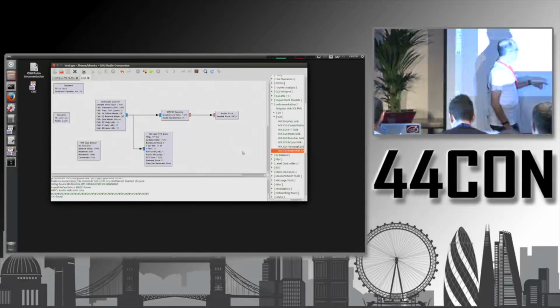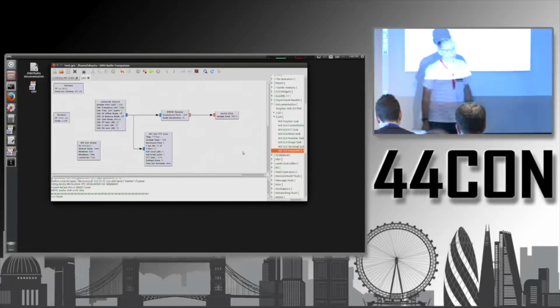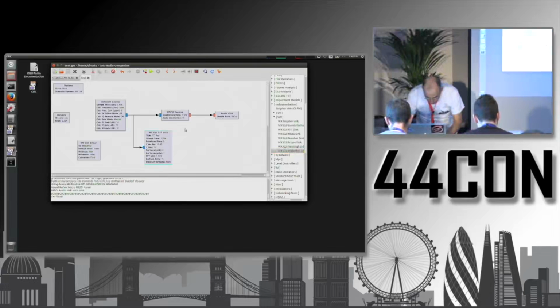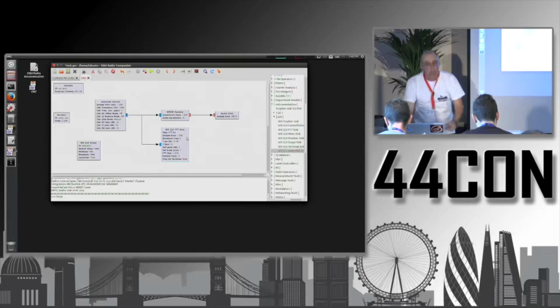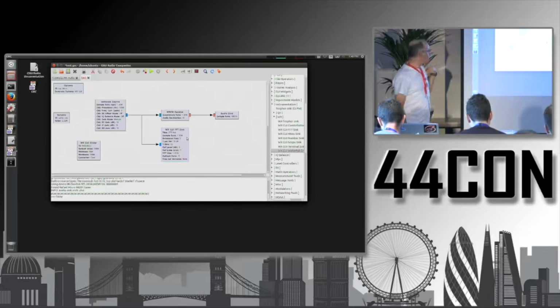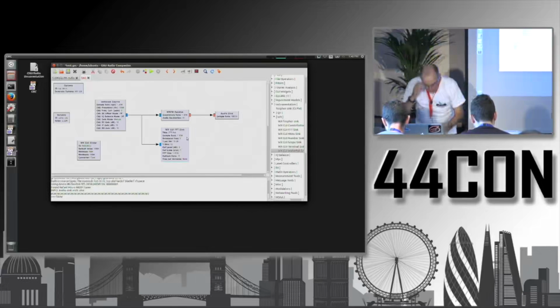Another nice one to add is a waterfall sink. So maybe for the people for whom that didn't work, just remove that FFT, the fast Fourier transform sink, and try just with a waterfall sink.